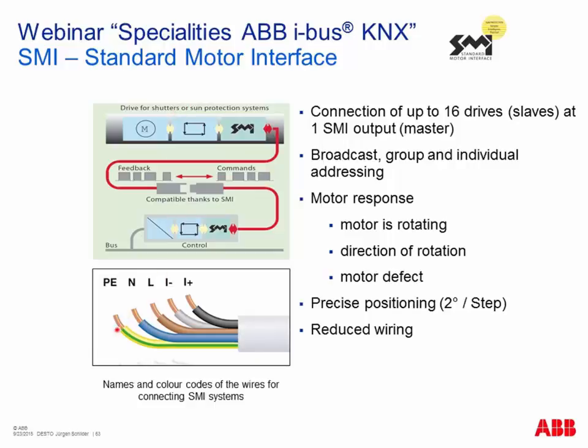So these motors need only the energy, the phase, neutral, protection earth, and two cores with digital signals to control the motor. So it works nearly like DALI. So via a special actuator it is possible to send commands to this intelligent motor, for example with very precise positioning. It depends on the motor, 2 degrees per step are possible.